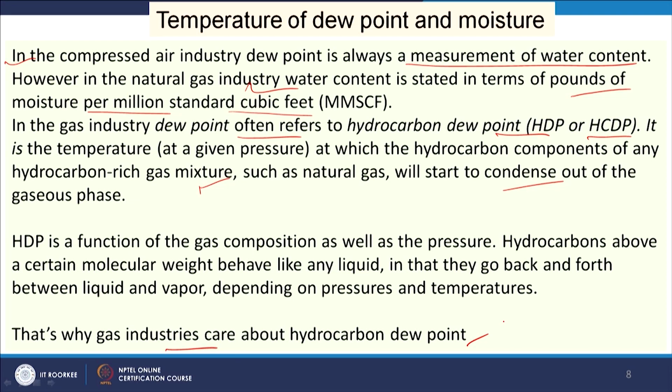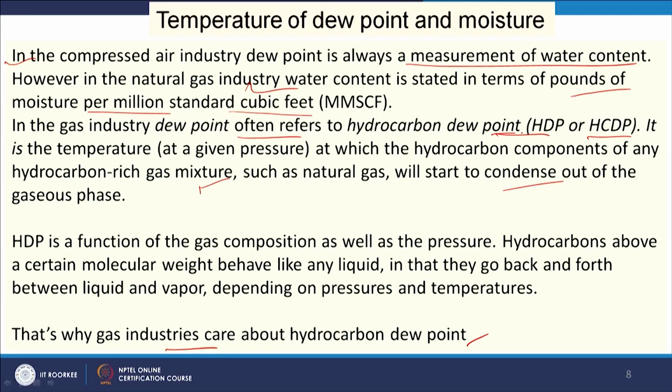Gas phase means it is easy to use, and the liquid phase, with higher hydrocarbons, gives us more heating value. So, the hydrocarbon dew point is important, as it will decide whether the hydrocarbon will be in the gas phase or the liquid phase. That is why the hydrocarbon dew point is considered by the gas industry.